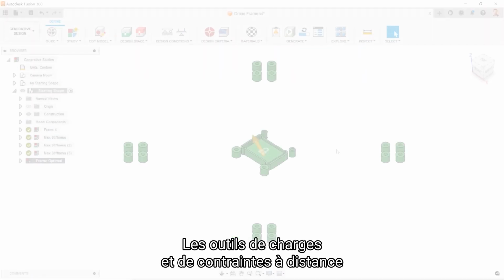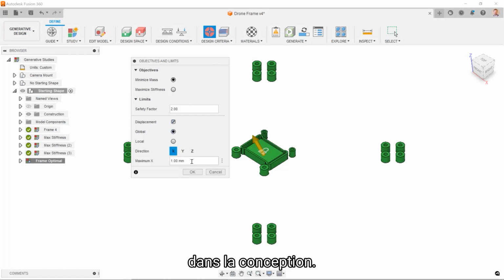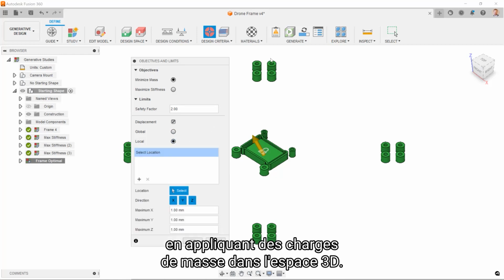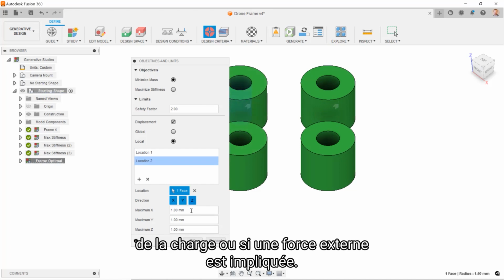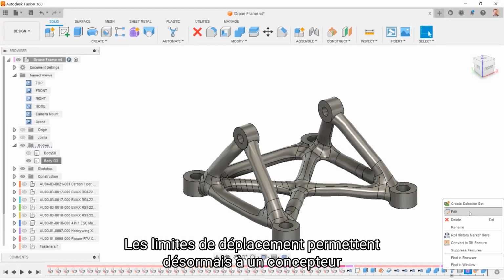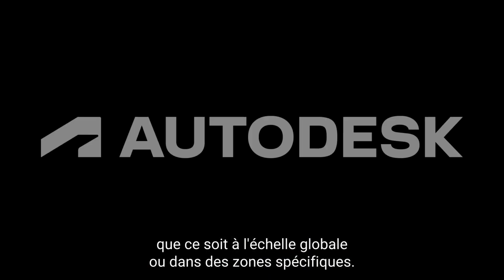The remote loads and constraints tools allow for creating designs that may be part of a larger assembly without knowing how the attachments play into the design. Point masses offer similar functionality by applying mass loads in 3D space. The primary difference between the point mass and the remote loads comes down to whether gravity is the load acceleration, or if there is some external force involved. The displacement limits now allow for a designer to specify how stiff a design needs to be on either a global scale or in specific areas.